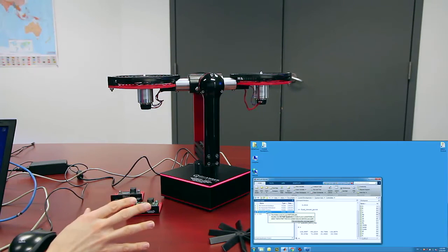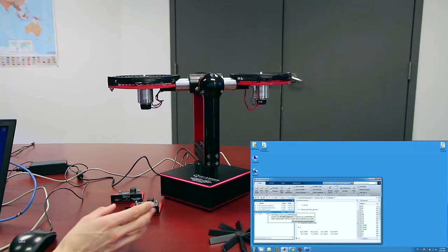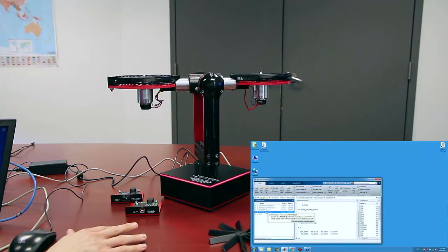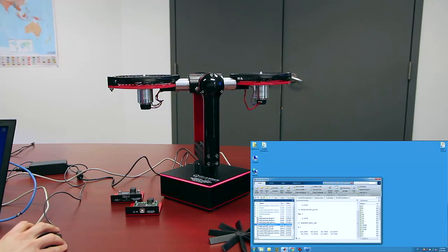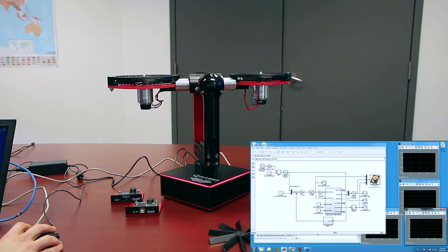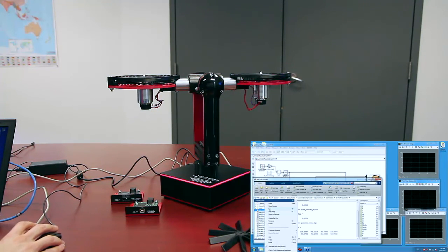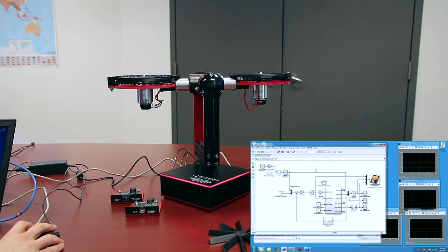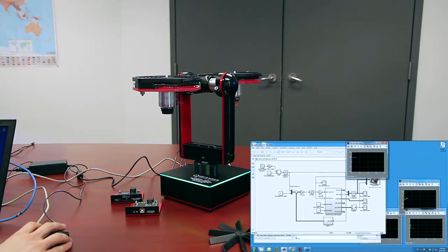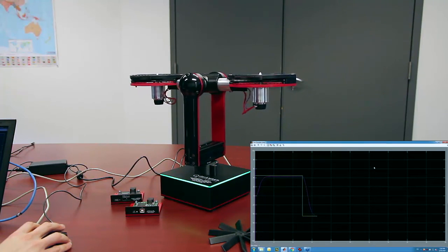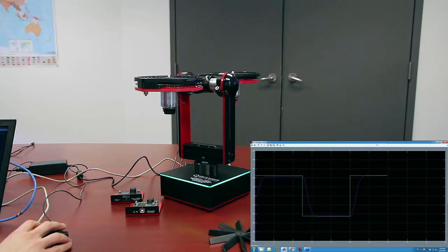So again, we developed the model for this, and we have two approaches: PID and state feedback using LQR. Also, we have a Kalman filter design to estimate the attitude of that. So let's go ahead and run that. I'm going to go straight to the LQR design here. Again, we have a number of scripts that we supply. So the half-quadrotor design, and we'll be changing the yaw plus or minus 45 degrees. So here is the quadrotor right there. It's doing pretty good tracking.